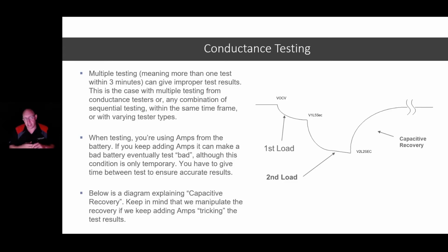The other component to this is the leads, the clips, the clamps of the battery tester need to be on the battery lead terminals. They need to be lead contact, okay, to the battery post. The closer you can get to the lead of the battery post, the better. Preferably on the lead of the battery post. If you have lead terminals hooking up, you can use those terminals because they're lead. You'll get a good connection as long as they're clean.